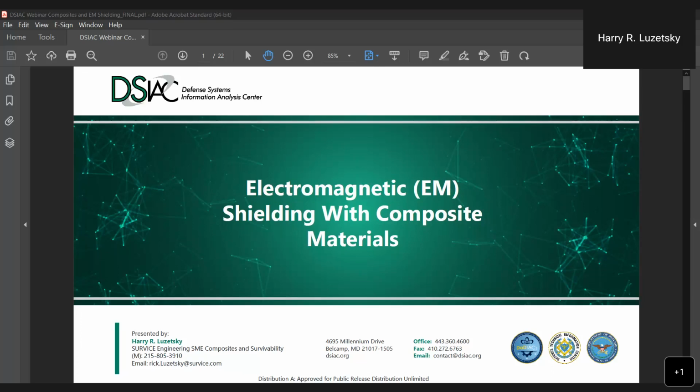Keep in mind too that the copper mesh is often used for lightning strike, and it is used as a grounding medium, so that when lightning would strike a vehicle, it's designed to have an attachment point and an exit point. My point being is that you can actually create those grounding planes within the structure, depending upon how it's going into the vehicle itself.